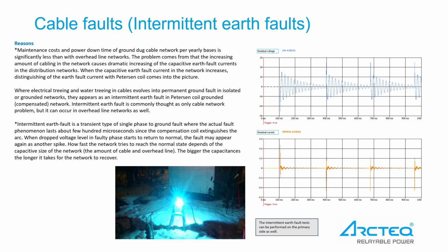The intermittent earth fault protection shall be coordinated with busbar residual voltage protection in such a way that in case of intermittent earth fault, the faulty feeder will be in all cases stripped by intermittent earth fault protection function prior to the residual voltage protection function, considering a sufficient safety margin as well. On the other hand, since an intermittent earth fault causes significant network stress, the protection trip should be performed as fast as possible.